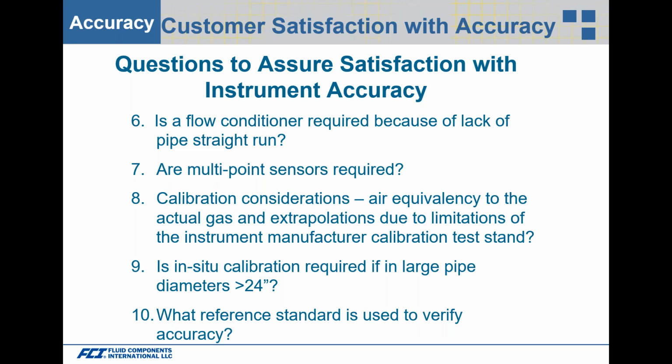So if your application is above what the test stand can do, then they just take that nonlinear curve and they extrapolate it out. That's not always the best situation. So you want to make sure that your calibration is performed on a test stand with the actual gas and that extrapolations aren't performed on it.